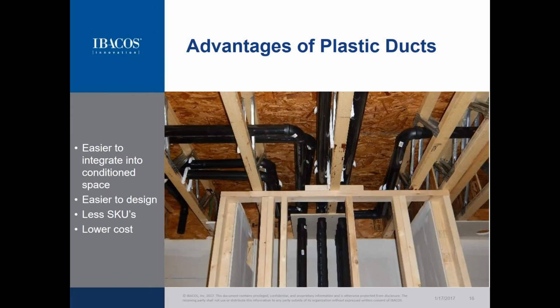So again, from some other aspects of designing with plastic ducts, again, easier to integrate. This picture that you're seeing here is our mock-up home in our warehouse that we had, open web floor joists, and you can see all the duct runs coming to a central location, where it's easier to route, and as you can see, there's a lot less components. One size for every room, and the elbows are very consistent, and it's easier to actually incorporate into the architecture of the home. And ultimately, it's a lower cost system.